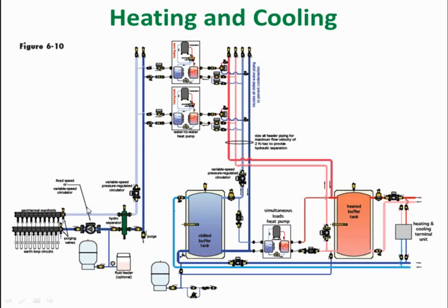If this is a glycol or a methanol or whatever transfer fluid you're using in this here, you can put a little feeder in, because if you start putting air vents on a system and they do burp a little bit of air out of there, now you've got the potential to cavitate that pump. So in this case, that being a heat transfer fluid, not just plain water, we would want to put that in through some kind of feeder or fill system. On this side over here, since this is just domestic potable water, we're feeding that with a regular expansion tank, and just one of our autofill valves could be used on that side.